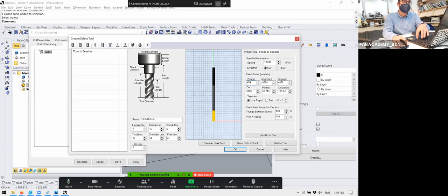If I'm in a hurry, 4,000. No, it's the first touch. Depends how you engage. There are two ways of engaging, that's later. And retract is getting out of the material. Here we are not cutting, so we can do the same. There is something called the CNC Cookbook, I think it's 1,000 pages for CNC machinists. They go really deep into these values. Like, no, it's at 30%. No, it depends on the style of end mill, etc. This can get really complicated as much as you want, but you can also simplify these values a lot.